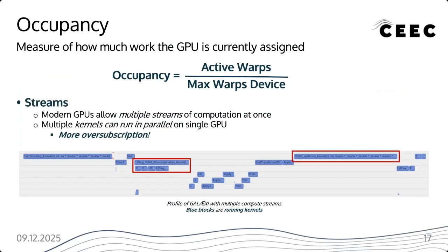And I'll point out over here on the right our volume integration kernel, which highlights that issue I just mentioned before, where this kernel has a very high register usage. And that means that we can't run anything else on the GPU while this kernel is running, because we don't have enough registers to run anything else.